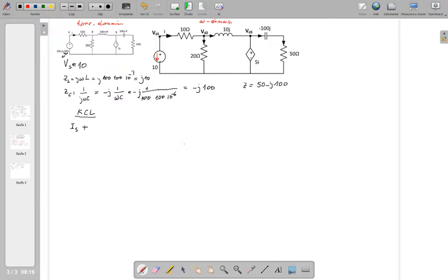And then we are going to write the voltage of this element in terms of node voltages. How am I going to write it? The beginning node of this arrow here is VD1. The sign we already said plus. Beginning of the arrow VD1 node voltage minus the ending node voltage VD2. So that's the voltage of this element. If I divide this voltage by 10, I end up with the current of this element.